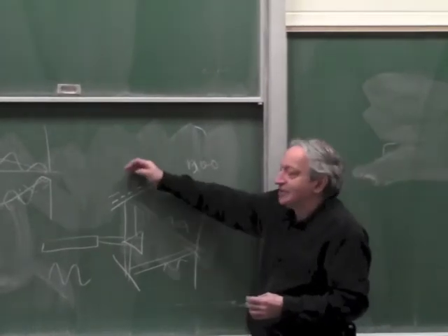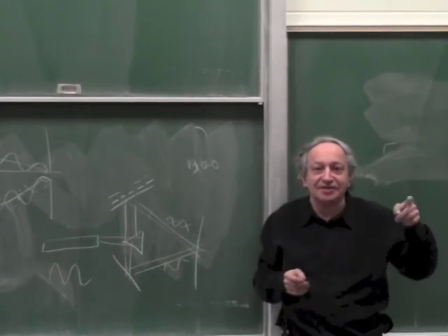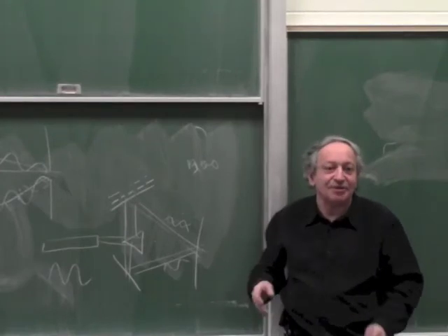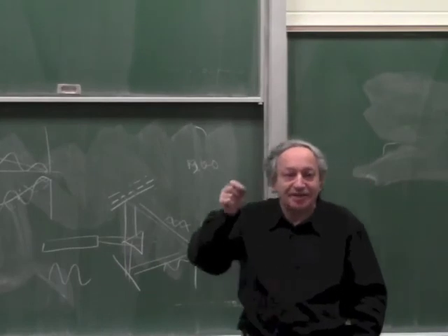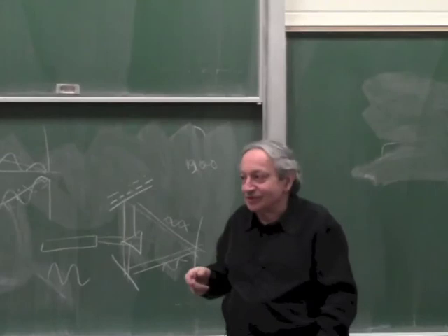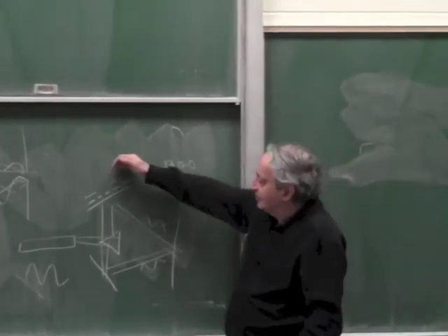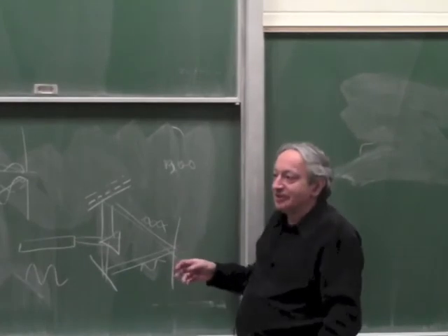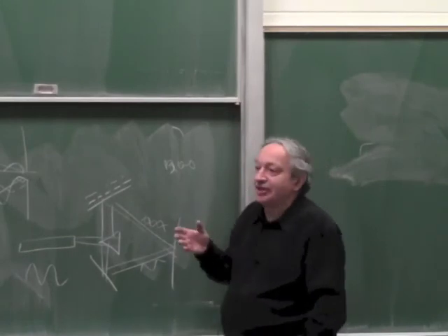But when I move this, instead of actual lines, I'm using the wavelengths of light as lines. That has huge advantages, because the wavelength of light is stable, you can make a long encoder, it's very fine. It's very difficult to scribe lines as dense as the wavelengths of light. So that is a perfect encoder. If I can move that, I can measure very small movements to great precision, and that's called an interferometer. This whole device is actually a position sensor.